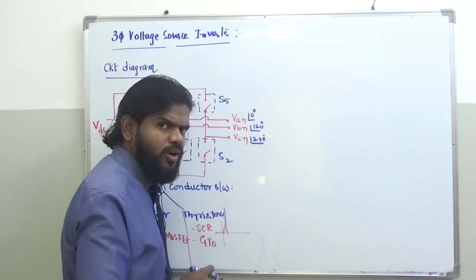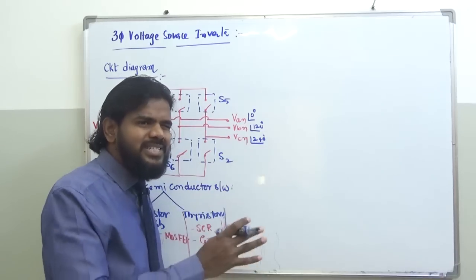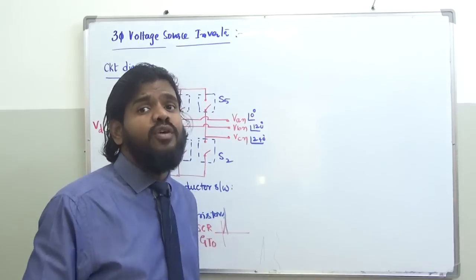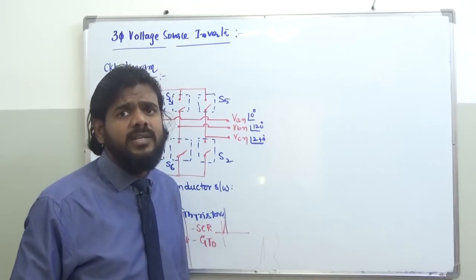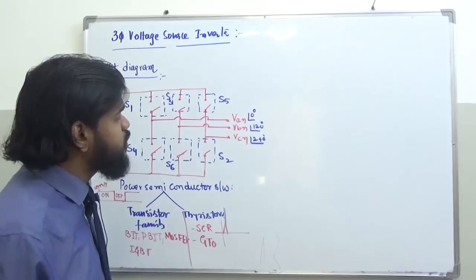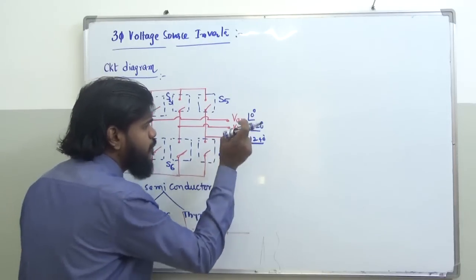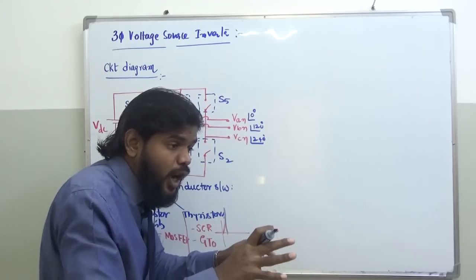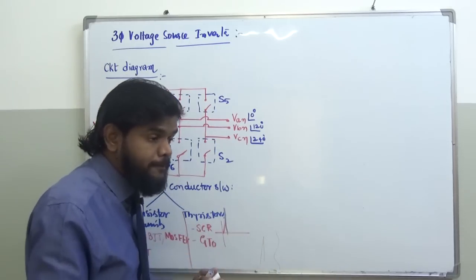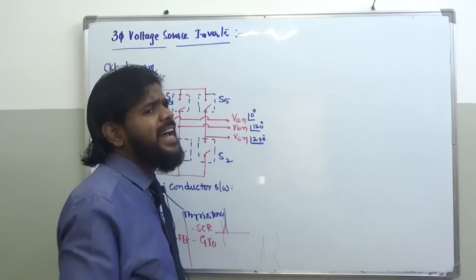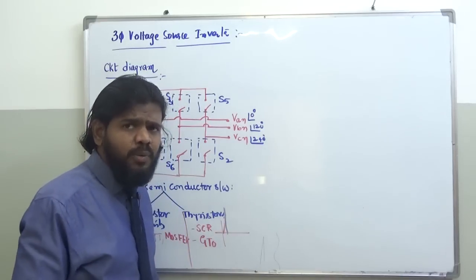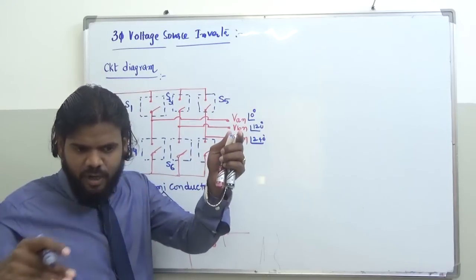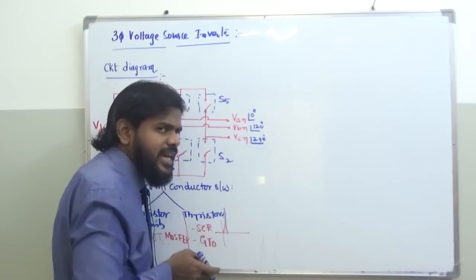And coming to 240 degrees, VCN will start its journey with a delay of 240 degrees. You can convert that into its equivalent time, 13.33 milliseconds. That's fine. So VAN, VBN, VCN are the expected output voltages, which start at different angles. Definitely there should be a 120 degrees difference: phase A will start at 0, phase B will start with an angle of 120 and phase C will start with an angle of 240.